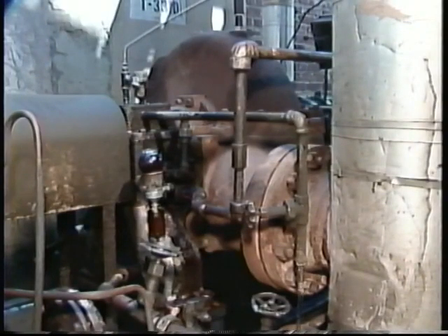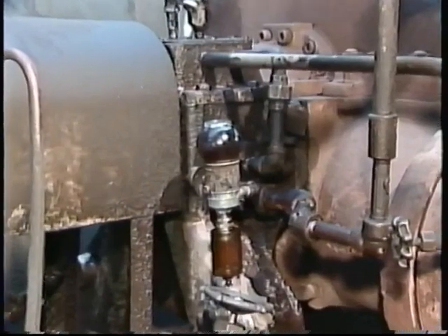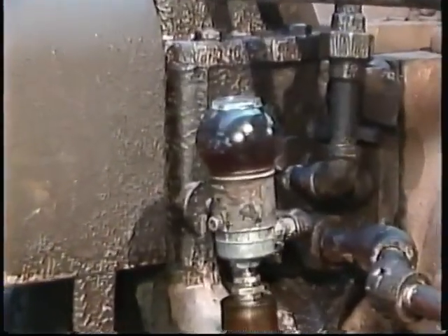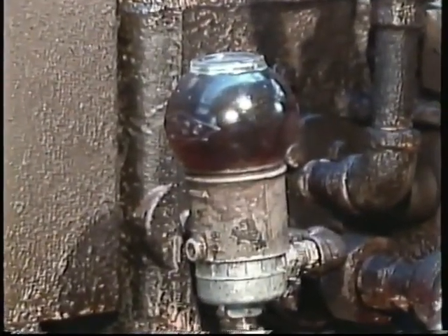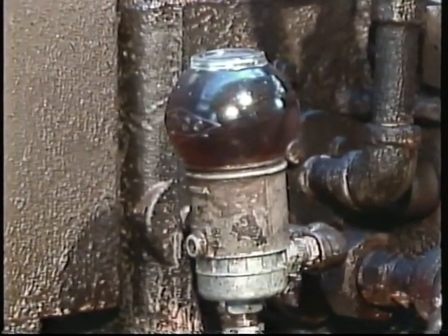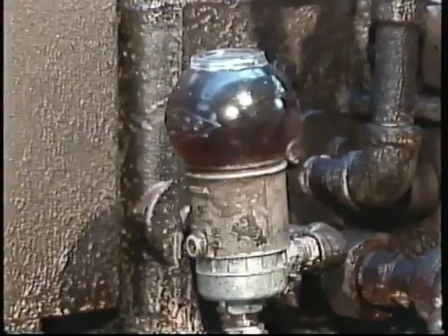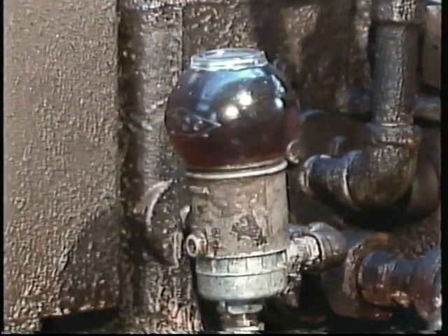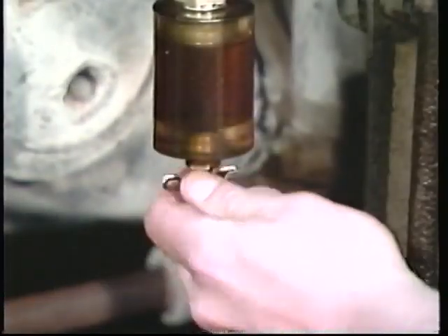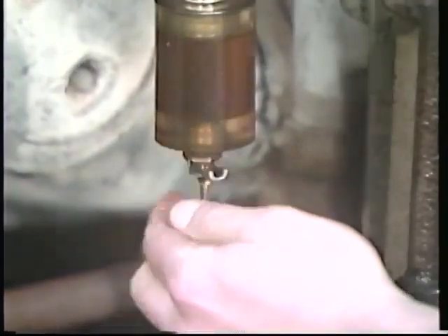Another major part of startup preparations is preparing the turbine's auxiliary systems. We'll start with the lubrication system. One critical step in checking out this system is determining if the oil level is adequate. In this example, the operator can check the oil level by observing a constant level oiler. He looks to make sure that the glass on the constant level oiler is full. The operator can also drain a small amount of the oil to see that it's clean and not contaminated.